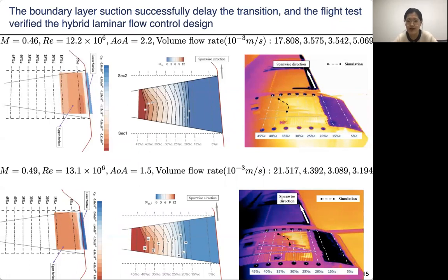Of course, we verified our code by using typical cases such as the airfoil and infinite span swept wings. We show those 2 experiments implemented by us to verify the code when it is used for the large sweep angle and high Reynolds number, which corresponds to the large civil aircraft.